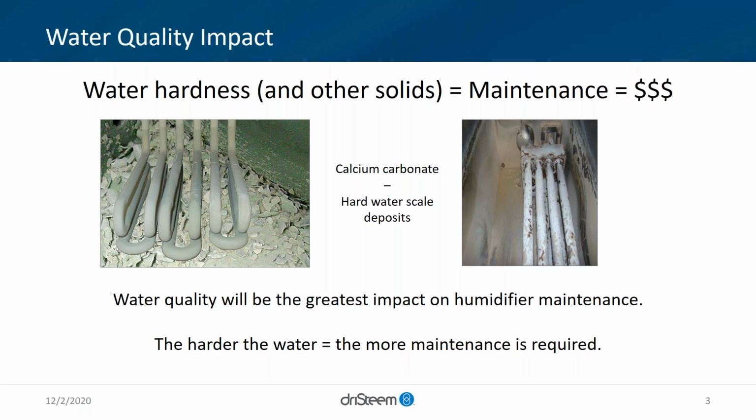In these pictures, we're talking about calcium carbonate, which is the most typical scaling potential as we're boiling water. That decreases your effectiveness in a lot of applications. And when you want to gain that efficiency back, you have to perform maintenance, whether that's a chemical cleaning or some good old elbow grease, getting in there and scraping off that scale from different surfaces.